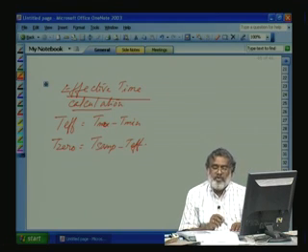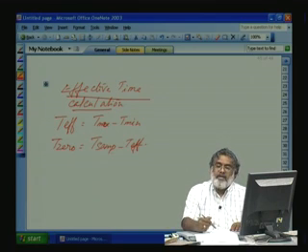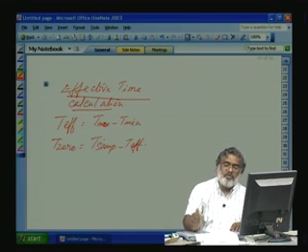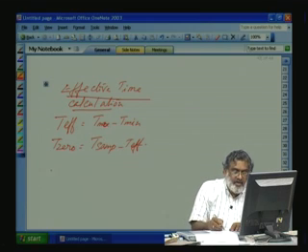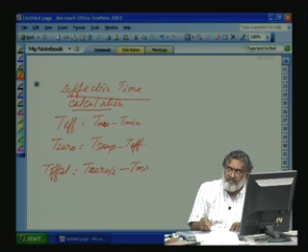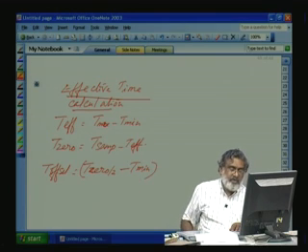Now we want to offset, because in all this period our TAS, TBS, TCS will have one maximum value and one minimum value. Minimum depending on the sector it will have minimum or maximum. Now for the gate signal we have to get the positive value. So we have to add the offset. The T offset to be added to all the TAS, T offset is equal to T0 by 2 minus T minimum. Okay.